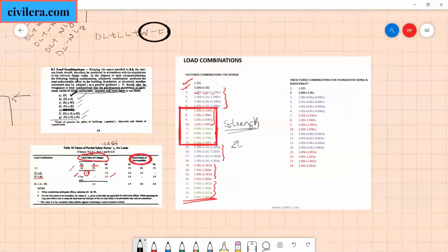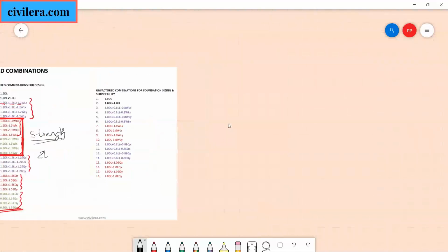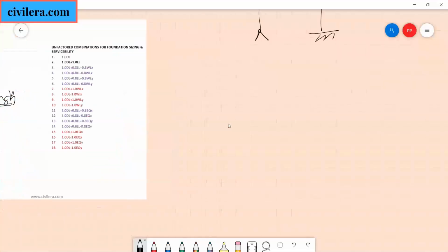Now, one more point, many engineers, even experienced, do not appreciate it really well. For foundation sizing, say if you have pinned your joint, you can pin or fix. That's a different thing altogether. We are not going to discuss that today. So when you pin your column, you will have a vertical reaction, vertical load on your column, which needs to be taken care of.